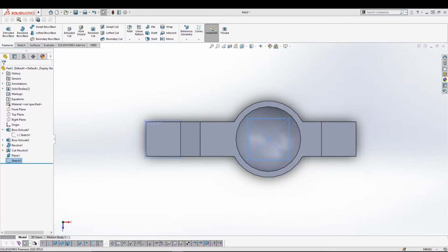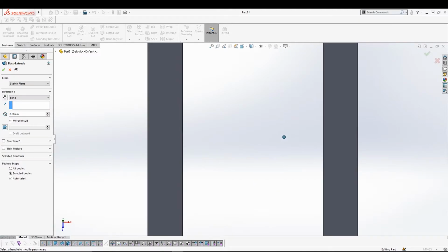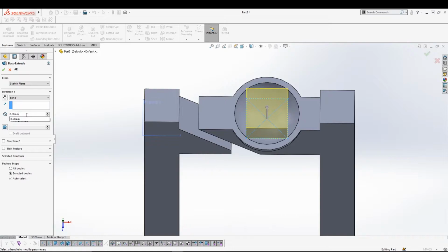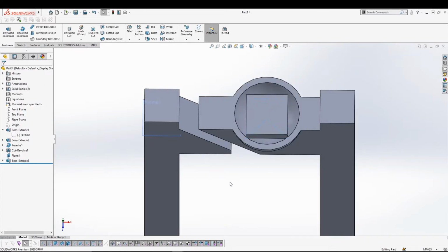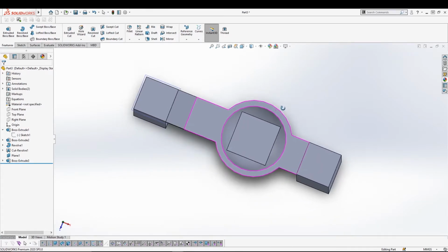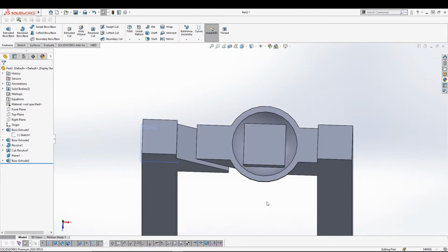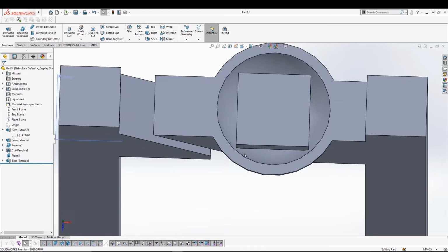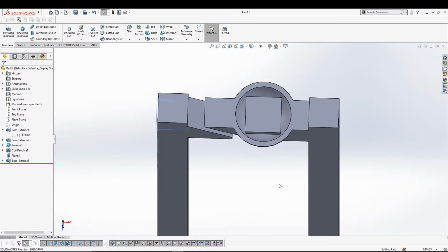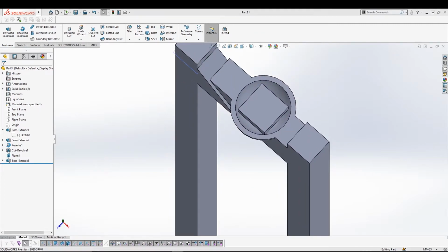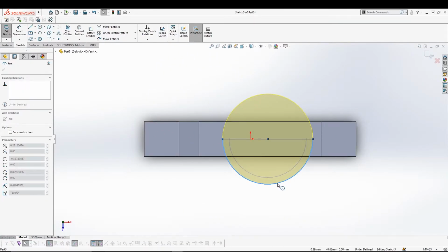and then I can utilize the extruded boss to give it a thickness. So let's say we'll go for only 0.2 mm. For the body, I'll select this one. Okay. Now in case you find it too close, you can always increase the two circles, and then if you have issues with the square part, you can do that. Alright, because our square looks a bit bigger than the circle. So let's say I will modify my sketch. I'll modify sketch 3, go to edit sketch. You can increase this like it.